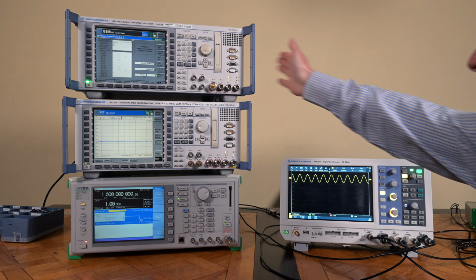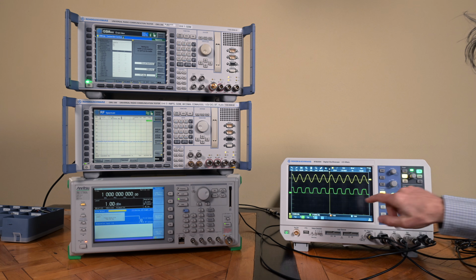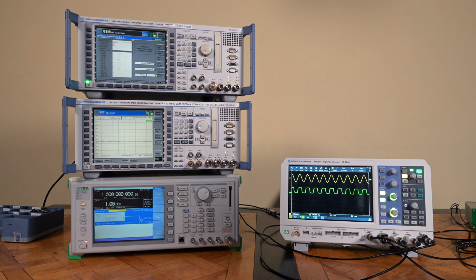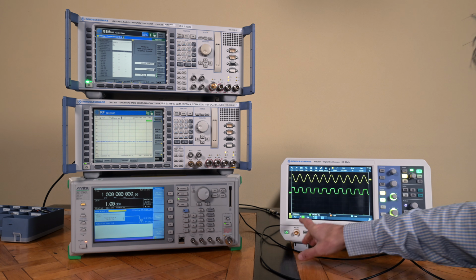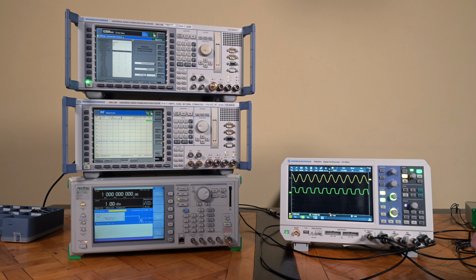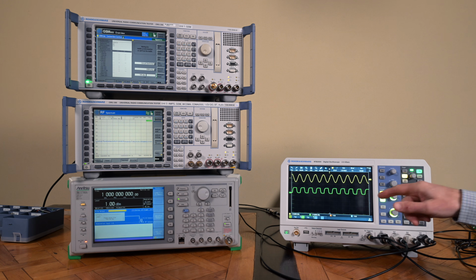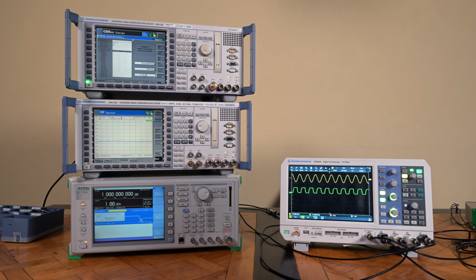So let's go and see, and we'll start with the CMU 200 right on the top of it. Let's activate that channel. And look at that. We basically see that it's 10 megahertz as well. We can measure it down here, but it doesn't make a lot of sense because its own internal source here is another source of variation. So it's better just to compare the two incoming sources here. So we basically see it moving compared to that. So we know it's not exactly 10 megahertz, but it's not terribly far off either. It's moving like 1 second every waveform.